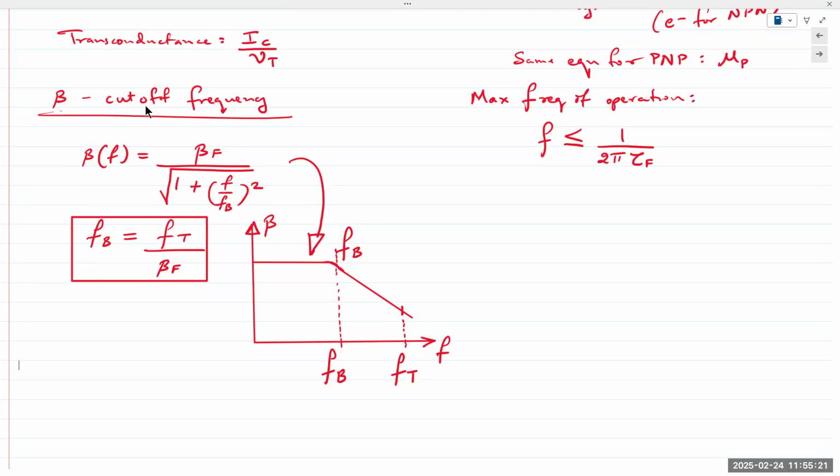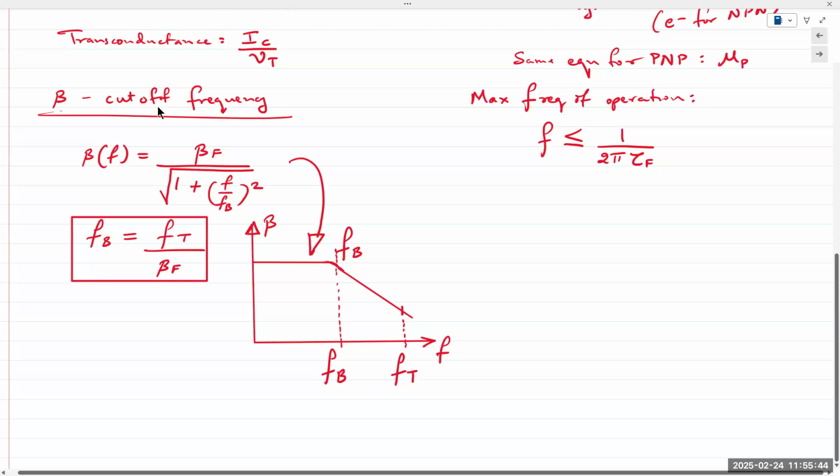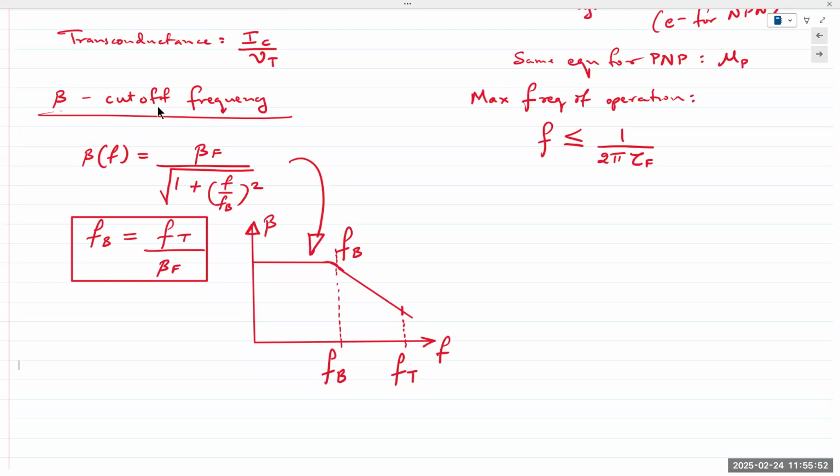All right, so let's take a pause. Let me know if you have any questions. So the question being asked is, why does it decrease, right? And you yourself gave one part of the answer: yes, because of the transit time, there's an upper limit on the amount of charge carriers that can transit through the BJT, which basically means the current would be dependent on that frequency. Yes.